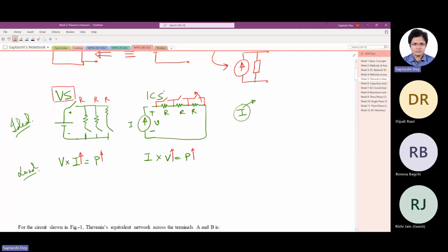Just hold for a second for that. So for a current source, we cannot do that. To turn off a current source, you connect a switch in parallel with the source. Simply close the switch. So you are short circuiting the source, and the whole current will flow through this switch. These loads will not get any current.